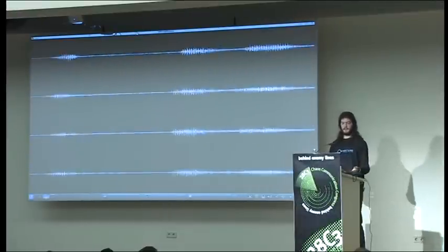It has a calibration sequence where each one of the microphones' impulse response from each one of these speakers is computed. And so with that, it can subtract out what the speakers are playing, so it can still hear you say Kinect while you're playing your game. And so you find all these things from the logs.